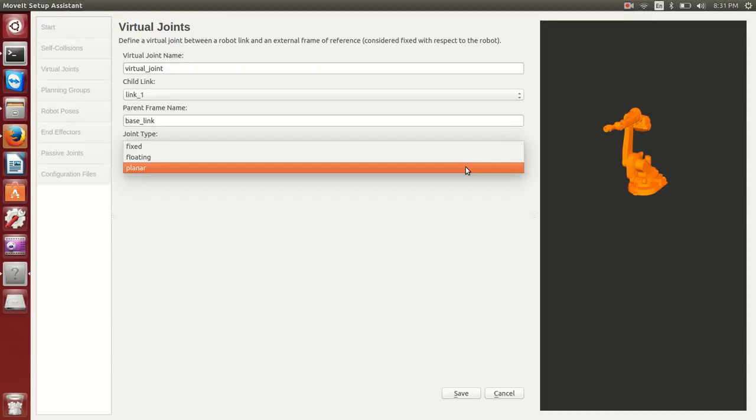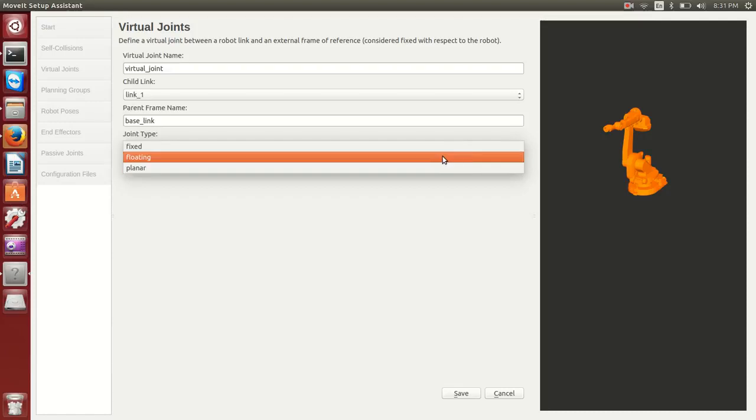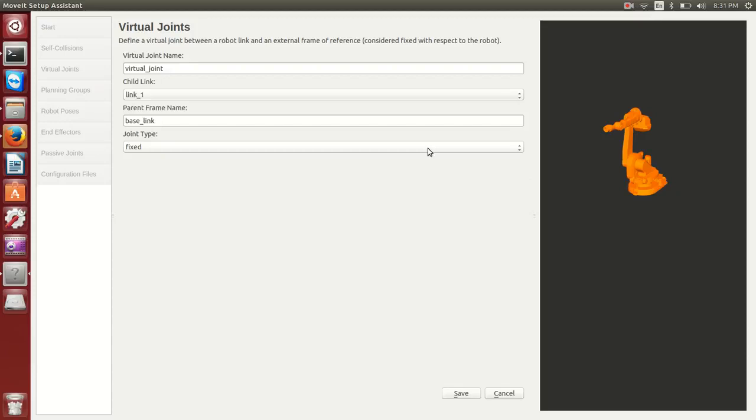It can rotate, go forward, and go sideways. In our case, I'm going to be using a non-holonomic robot, which has 2 degrees of freedom, forward and rotation. It's actually a skid steer robot, which essentially is a differential steer robot. Anyways, I want it to be fixed.